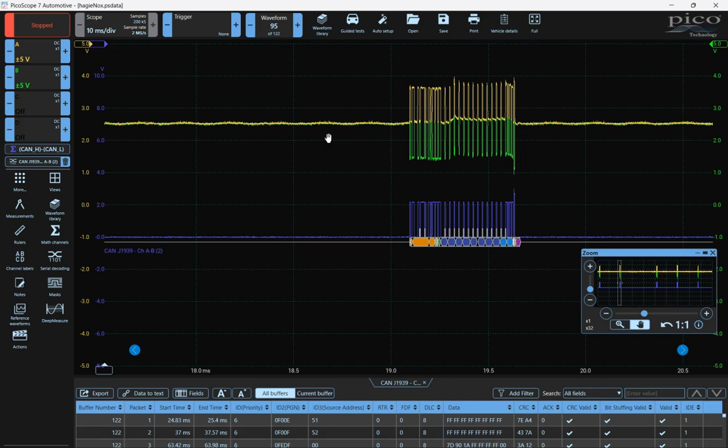Part of the reason, to get into this CAN bus, I had to remove one of the terminating resistors, a passive 120 ohm terminating resistor. I put my scope leads where the terminating resistor was, because this data link does not go to the 9-pin diagnostic connector on the machine. This is the after treatment bus, so the rest of the machine is not connected to this, only those after treatment components. So if we look here, we can see a little bit of that waviness, but we really don't care, because the CAN transceivers that are in each of the controllers look at the difference between CAN high and CAN low in reference to ground.